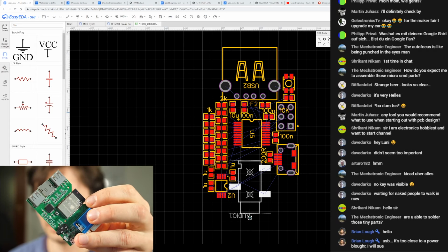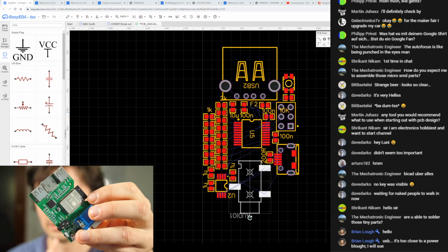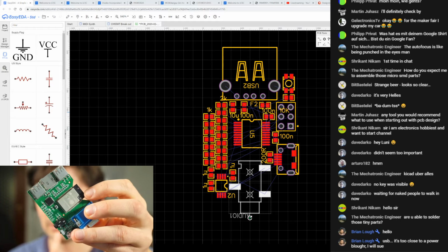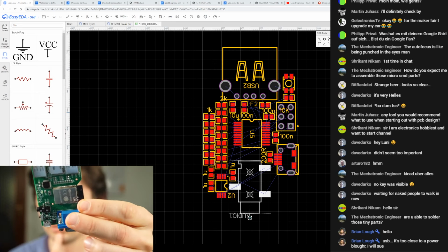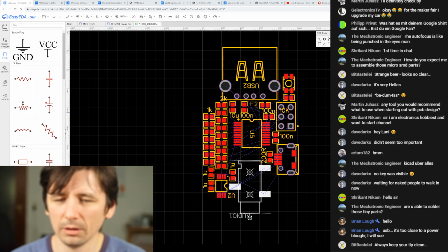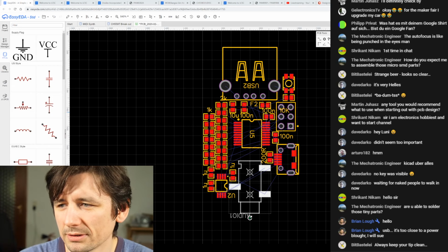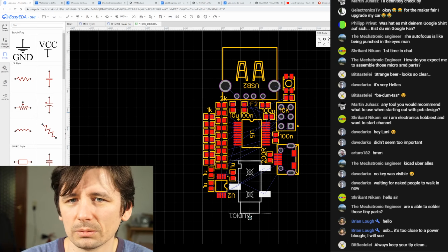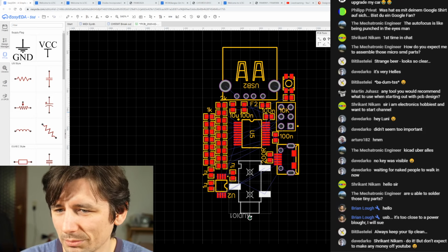I don't think that I have a stencil for that. I might have even soldered it. I might have a stencil, I don't know, but that whole thing was hand placed. I don't use 0402 parts, only 0603 or 0805, so I'm able to work on my prototypes and maybe botch them if needed.